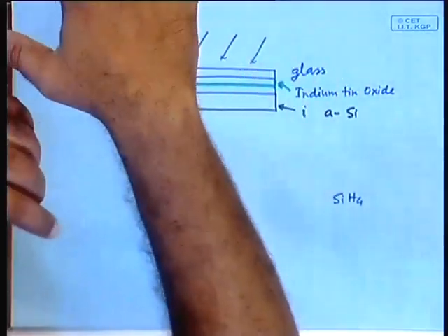While it does so, silicon will have a lot of dangling bonds. Then some of these dangling bonds are satisfied by that excess hydrogen which is again separated out, that is also in that environment. That hydrogen satisfies some of the dangling bonds, as a result forms what is known as not exactly silicon, but silicon hydrogen alloy kind of thing.